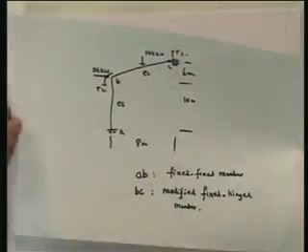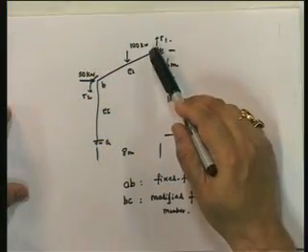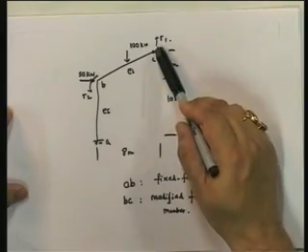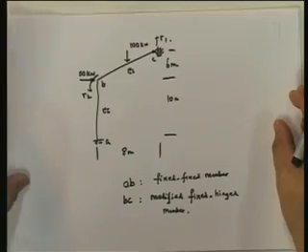Okay. So, let us see how we proceed with that. Well, we already know that this is a 2 degree of freedom structure. There is a third degree of freedom, which is the rotation at this point, but since we are considering the fact that the moment at this point is 0, this is not an essential degree of freedom, and so we are left with 2 essential degrees of freedom in this particular structure.